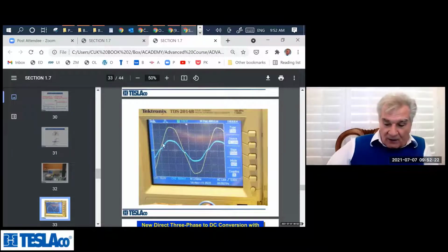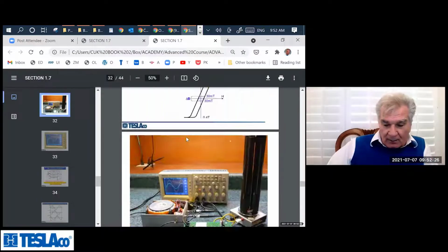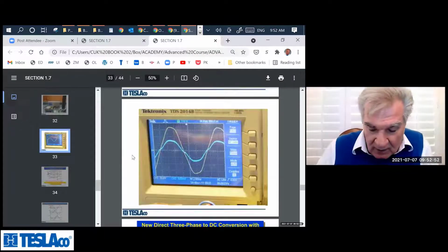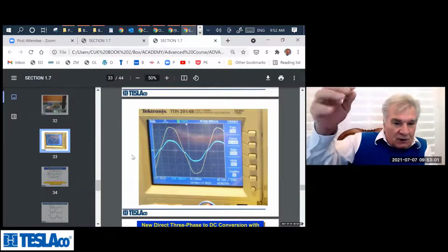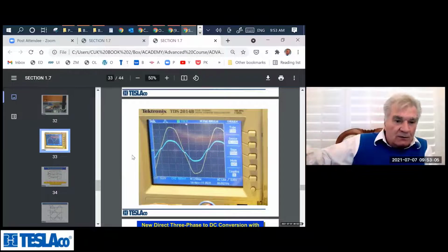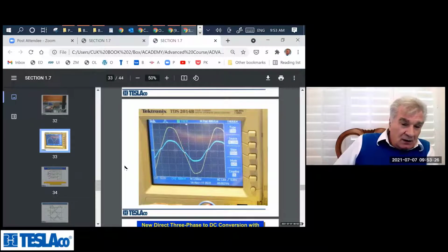Okay. Anyway, so we go further down here, and you see just one comment. You see what happened at this instant: this is the moment when the sine wave changes from positive to negative. This capacitor has to be charged from 0 DC voltage suddenly to the DC voltage, which is now equal to the output voltage. But because that's happening at low voltages, this glitch very little affects the performance, because measurement shows the power factor is still 0.999 and total harmonic distortion is 1.7%. And you can operate on both 110 or 220 lines, so you can get decent harmonic distortion even for a 220. In other words, you can operate on both 110 and 220 and still have this thing operational.